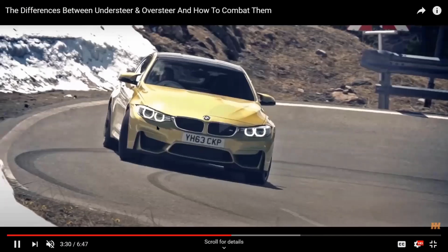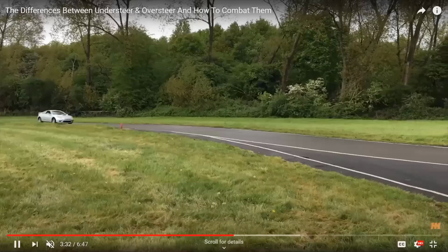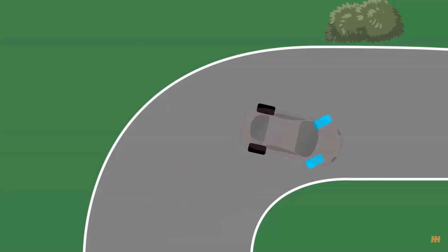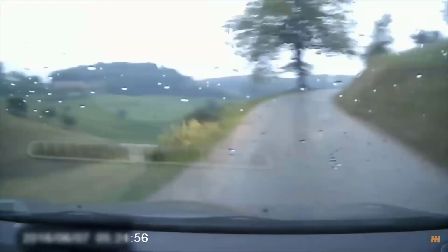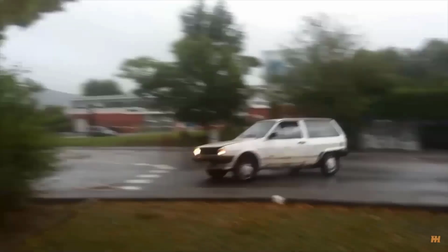Because of that, the CG is shifted and oversteering is happening. Okay, body slip angle: the vehicle is moving more than the intended steering we are giving, so the body slip angle is increasing. So this is dangerous while driving for normal drivers. An experienced driver can do it.